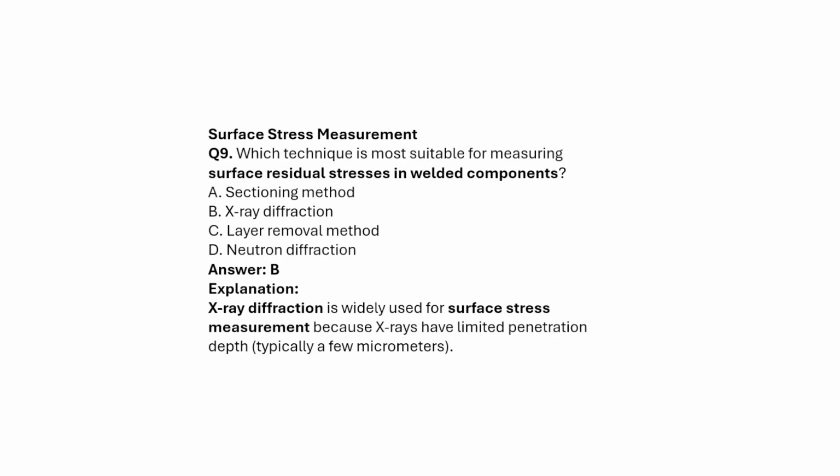Which of the techniques is most suitable for measuring surface residual stresses in a weld component? Okay, sectioning method, XRD, layer removal, neutron diffraction. The sectioning method is a much more tedious process as we have to cut each layer and measure it, and it is also a destructive process. While with X-ray diffraction we can measure in a few minutes, and layer removal is also a tedious process.